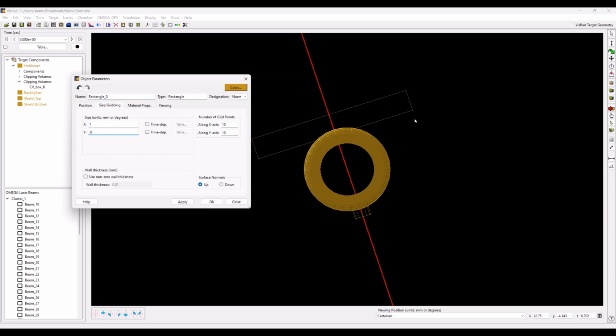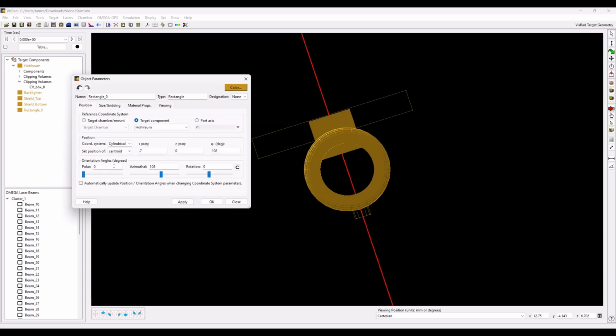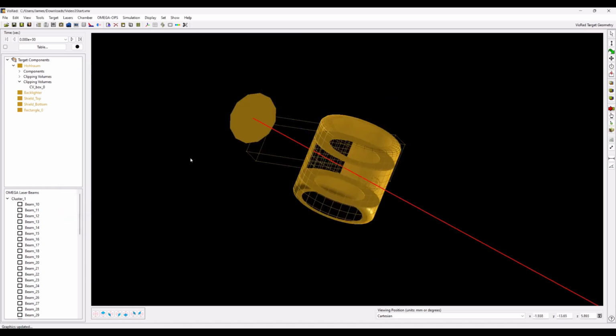And for the X, it's a little trickier because you can't just use 0.8. We want to find the length of this cutout through the whole realm. So if you just use some basic trig, you see it comes out to be about 0.7746. And if I hit apply, we generate our sample, but it's a little flipped. So I can just flip it by changing the orientation here to 90. And there's our sample.